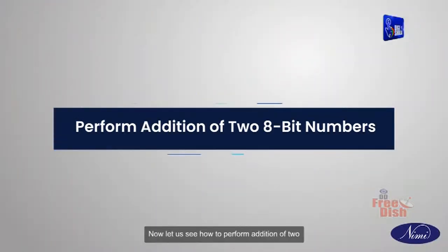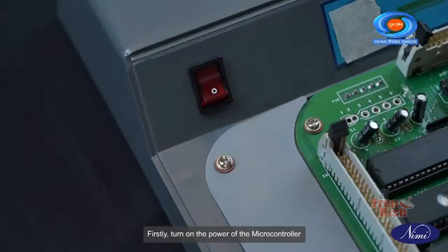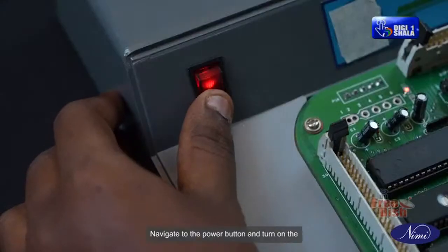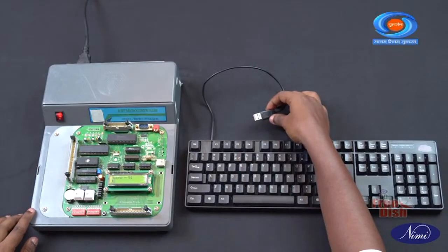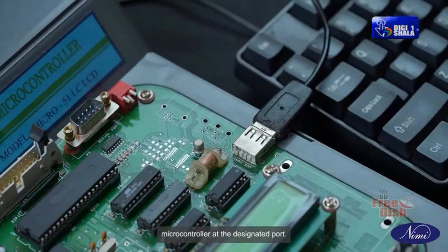Now let us see how to perform addition of two 8-bit numbers. Firstly, turn on the power of the microcontroller kit. Navigate to the power button and turn on the switch. Now for writing the code in the microcontroller, externally connect a keyboard to the microcontroller at the designated port.